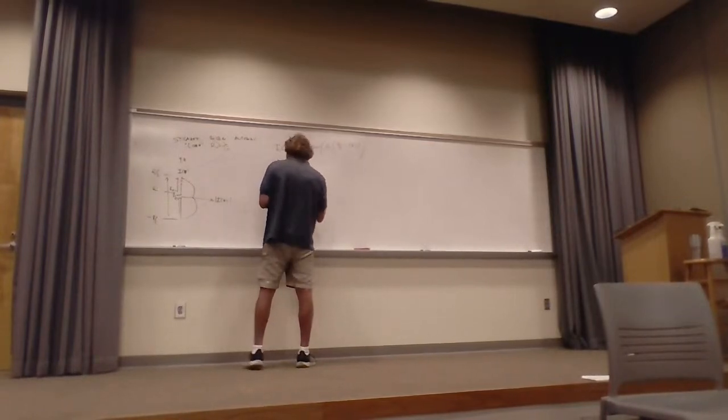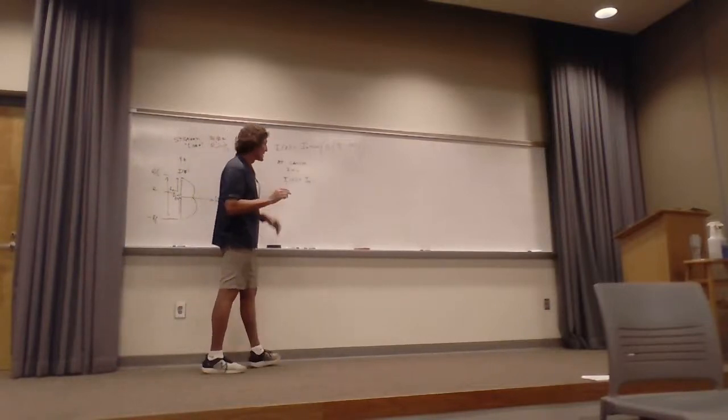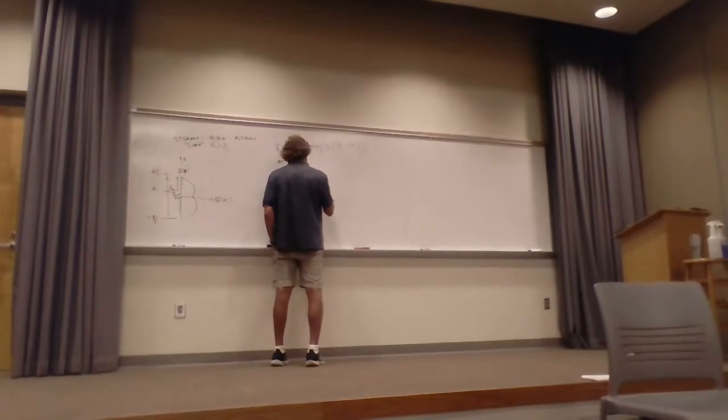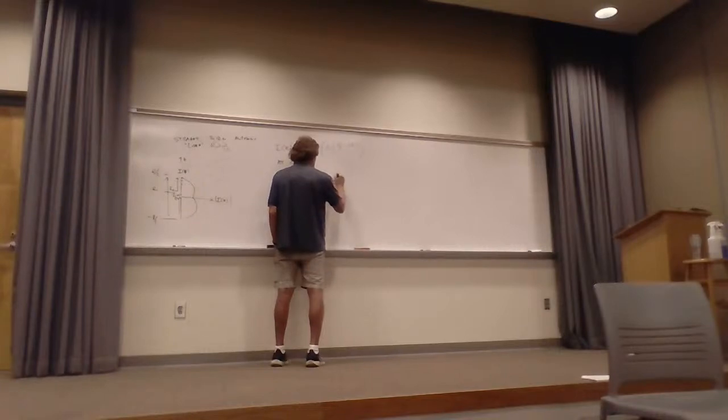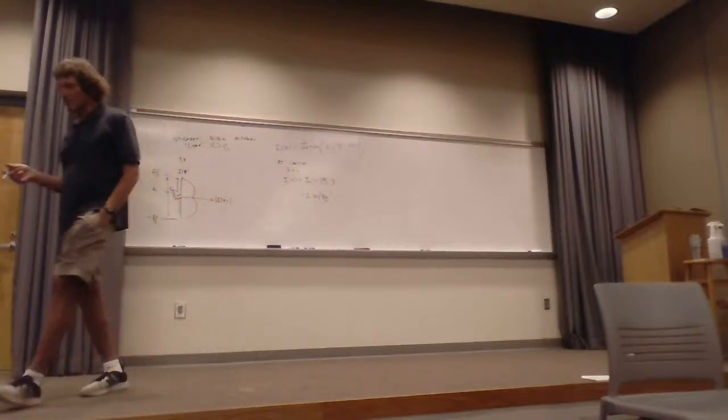Now that I naught is the current that's feeding right here. This is where it gets a little crazy. Then it's going to be times the sine, right, of beta L. Well, beta is 2 pi over lambda, right? Times L over 2. So that's equal to I naught times the sine of pi L over lambda. Just work with me on this one. Y'all follow me? This is the thing that's going to bother me.